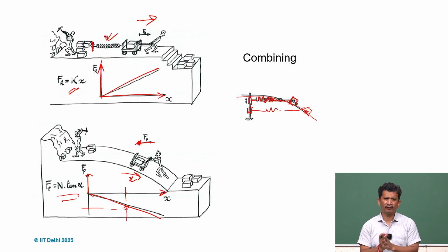And many times, suppose we are looking for zero stiffness so that it can stay anywhere, or for many vibration isolation cases, or even for some vibrational characteristic, we may want to have a very small k. In those cases it's very difficult to directly design something with a very low stiffness. But if we combine the two, we can get near zero stiffness, and we can fine tune the vibrational behavior of the system.